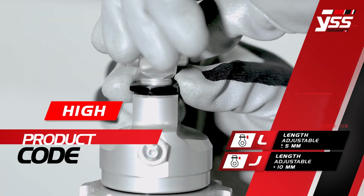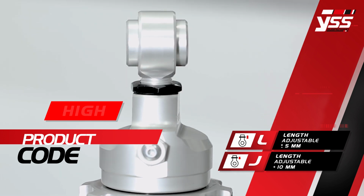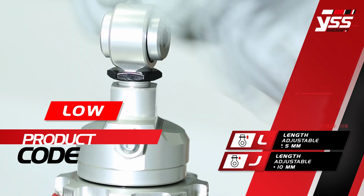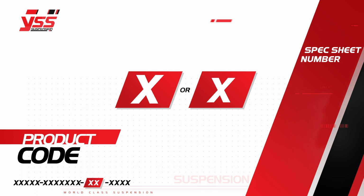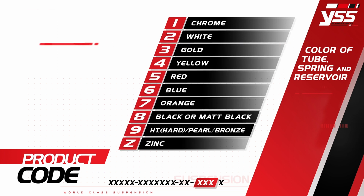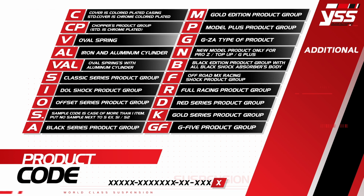L or J: Length adjustable helps increase or decrease the length of the shock absorber, which can be adjusted in 2 ways. L can be adjusted between plus or minus 5 mm, and J can be adjusted within 10 mm. Digit 15 to 16, running number. Digit 18, 19, 20, shock absorber tubes color code, springs color code, and reservoirs color code. Digit 21, additional product code.